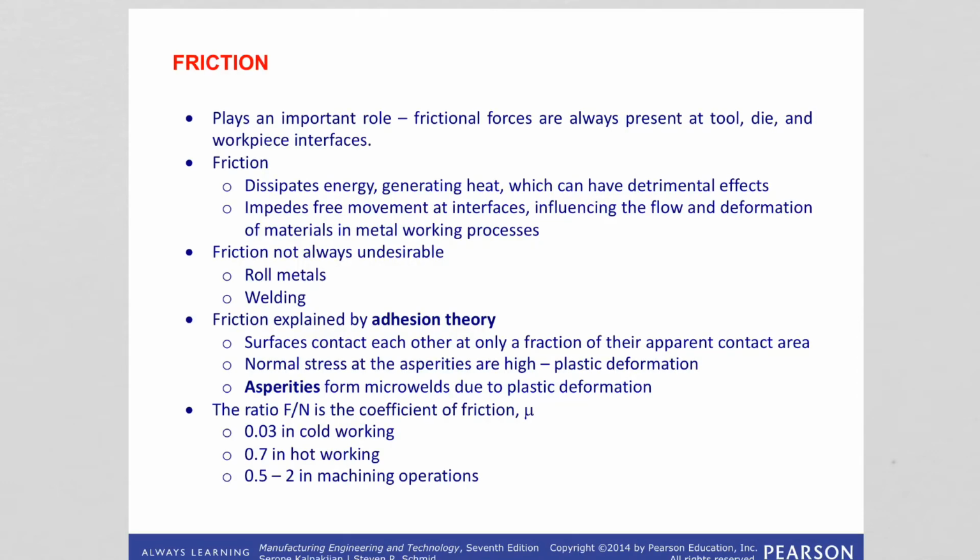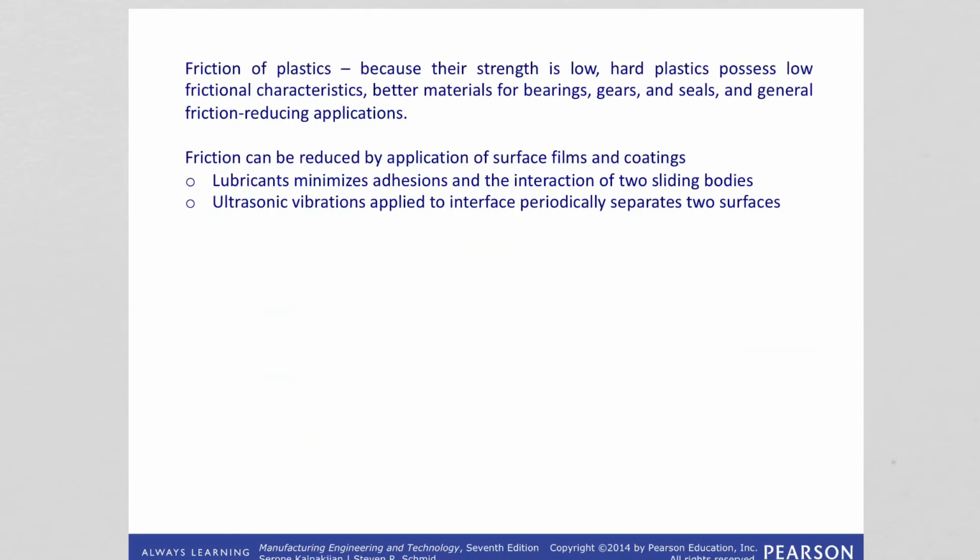Okay, so another theory of friction is abrasion theory. In this case, it is based on the fact there is a hard surface, such as a tool or die, which penetrates or plows a softer surface, and plowing will cause displacement of the material. In any case, for both theories or both situations, the sliding of two bodies in contact will require a tangential force, and this force is called friction force, as you see in this image here.